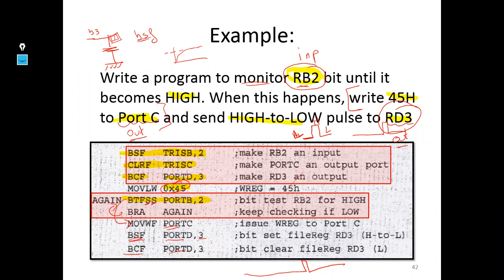Okay. So for the input, if you are reading from the port, you are reading the real value that you have in the pin. If you are reading from the latch, you are reading the value that you sent previously to the latch. This is the difference. So to switch on or switch off, you can use either the latch or the port. For reading, I give you the difference between the two possibilities. Okay. If you have resistive load, it doesn't matter. You can read from the latch, you can read from the port, you will read the same value.